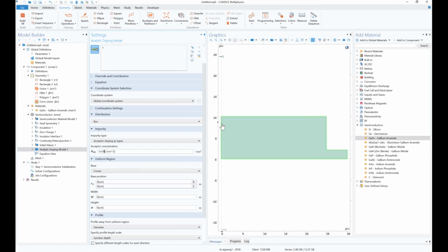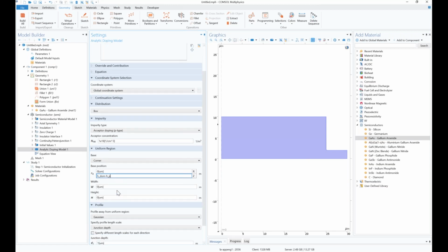Okay, that will be from the top. This is the width and depth of 2.5 micrometers. So we can define here first the 0, then the position is the domain height minus the doping depth profile, and the width will be the whole domain width, and the height will be the H_p.